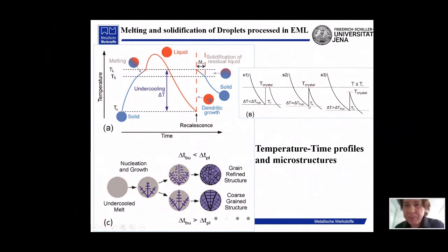So there is another type of crystallization which is consistent with hypercooling. If the initial undercooling, defined by the difference between liquidus or melting temperature and nucleation temperature, is equal to the hypercooling, then we have no plateau duration at the crystal temperature. We have only one point, so recalescence leads us to the point, and then undercooling is enough to accumulate all latent heat, and we don't need outer removal of the heat released during solidification. Because of this, we have only one point and then further cooling down.